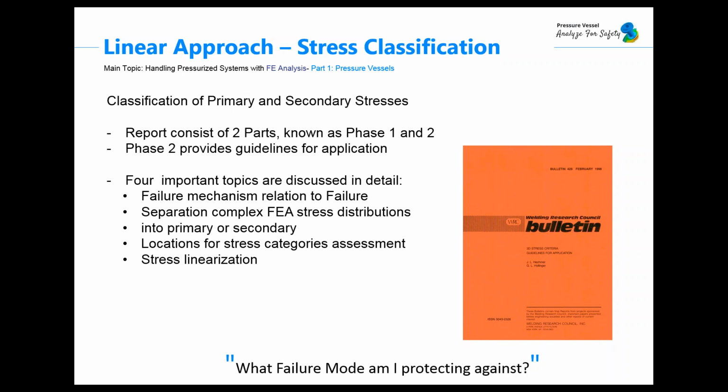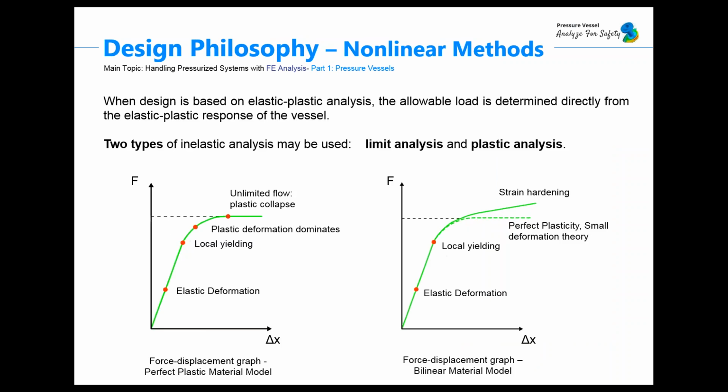So you can find inside a lot of important topics, like how to relate the failure mechanism to the failure, how to perform this separation process, how to classify these stresses into primary and secondary. Actually, it's not about how to classify, but it will provide you the guides on how to start. And of course, it's about the stress linearization. And now we are starting to talk about the nonlinear methods.